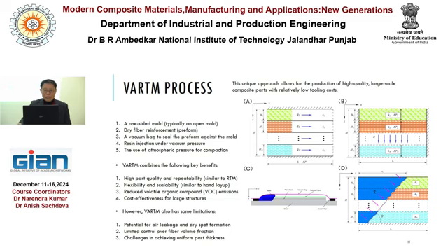And the dry fiber reinforcement, preform, is used. That means it is very easy to be placed on the mold. And the vacuum bag will be used to seal the preform against the mold, acting like the upper mold.